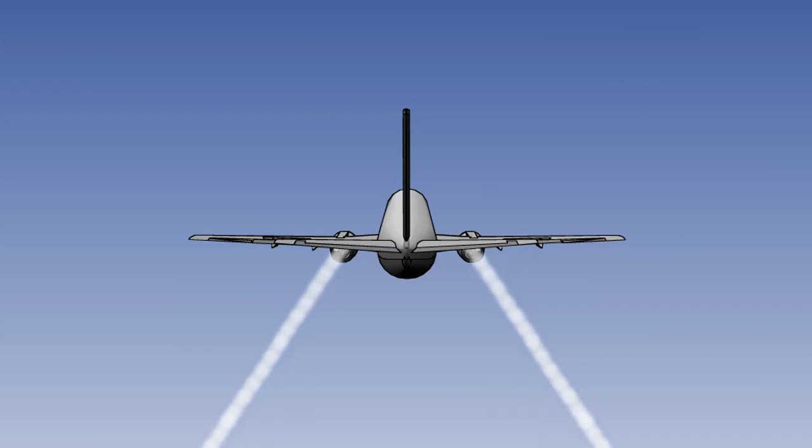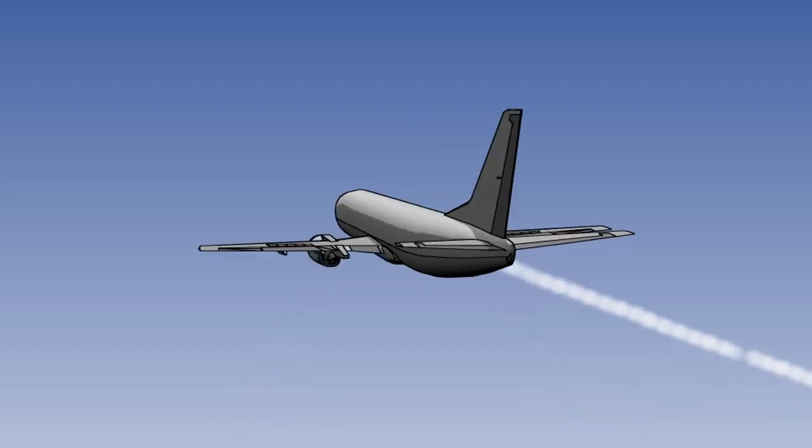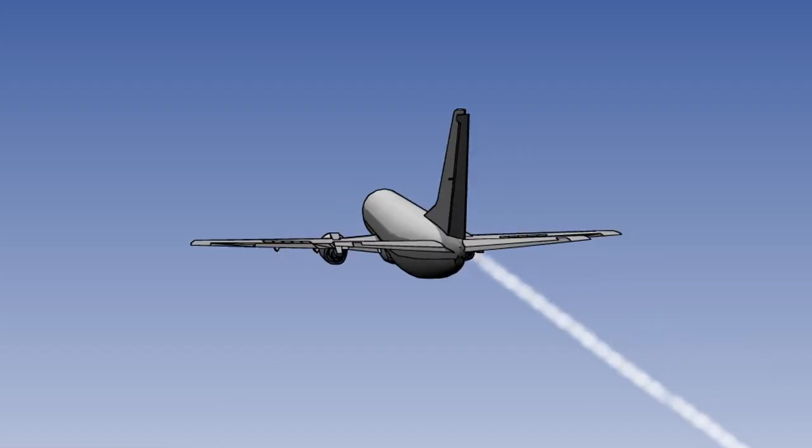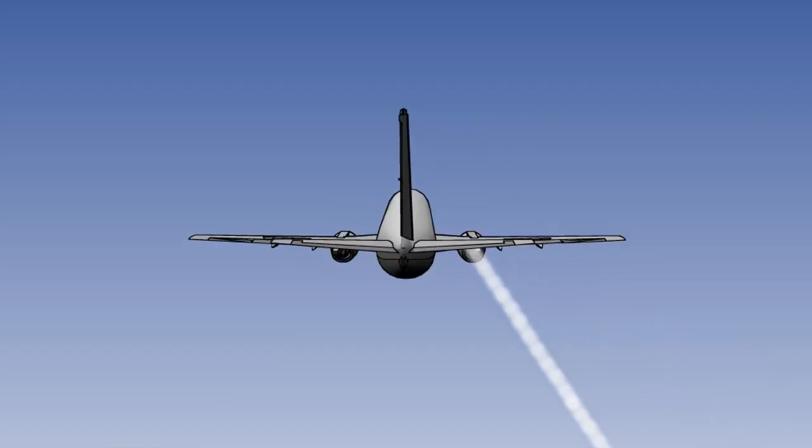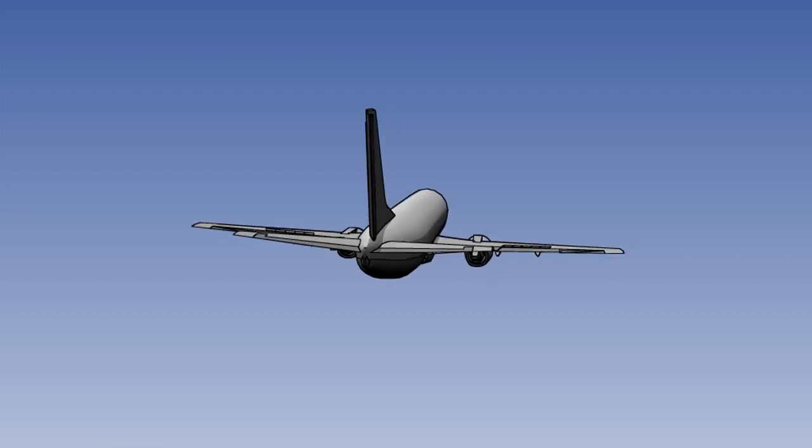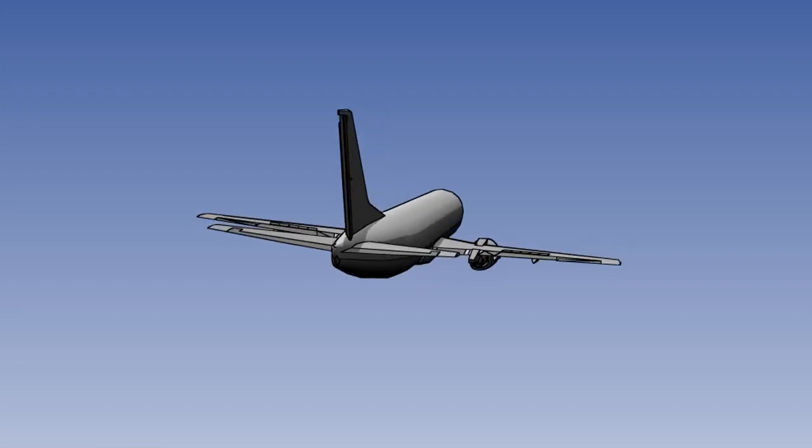As well as yaw damping, the system can be used to aid the pilot when an aeroplane suffers an engine failure. The yaw damper will sense the yaw towards the dead engine and apply opposite rudder to counter most of the yaw effect. The system could also be used to aid in turn coordination by applying a coordinated rudder input.